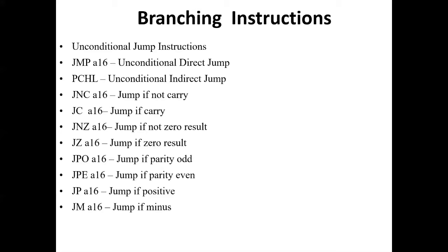Next is JC A16. JC is a mnemonic which stands for jump if carry. This instruction is used to jump to the address A16 provided in the instruction only if carry flag value is 1. If carry flag value is 0, program flow continues sequentially.